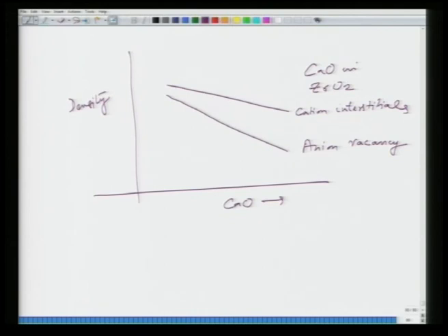So, what we have discussed in this module is basically the defect equilibria. First of all, we started with how the defects are formed, what are the various defect reactions, how we can treat these defect reactions as chemical reactions, the basis for that, and we also worked out how the equilibrium concentration of defects is calculated, what happens when you put impurities inside a particular material, and then we looked at the concentrations of defects at various partial pressures of oxygen by creating the limiting conditions in high and low pressure range and created an equilibrium diagram. And finally, we took some case studies just to see what kind of defects dominate in which kind of material.